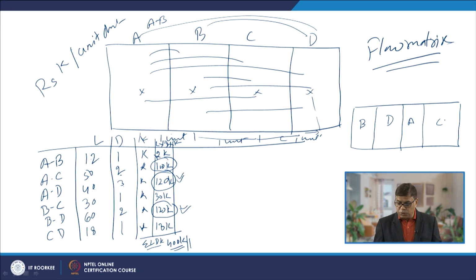The centers which were causing the higher cost, like A and C, were causing the high cost of 100. So they have been brought next to each other. D and A were causing the high cost of 120. So they have been brought next to each other, likewise B and D. Now the load will remain the same, but the distances to be travelled will get modified.